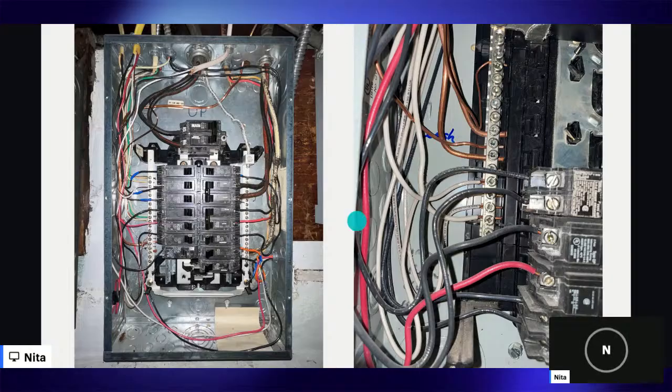So now when you're looking at your panel and you see your bus bars, as soon as you see these copper wires are thicker than any of your branch circuits in the box, that automatically lets you know, oh, this is my grounding system in full effect. This is my GEC. I know you'll be able to follow it up and out.